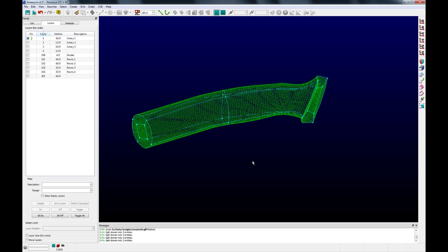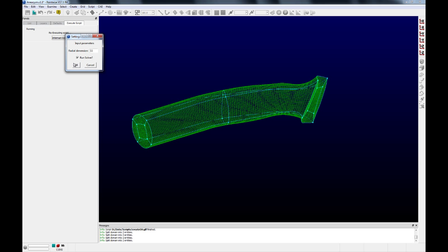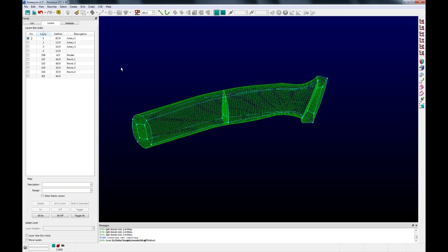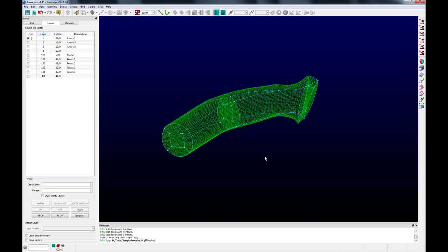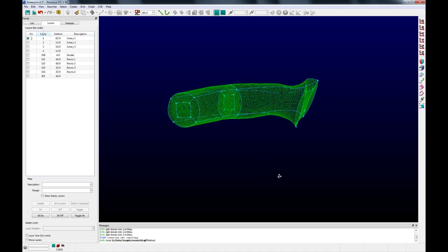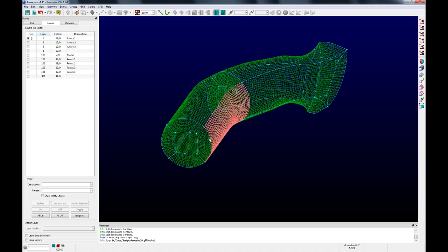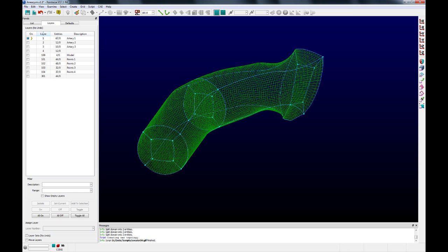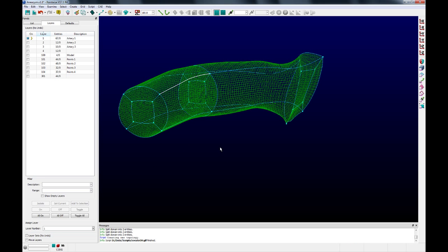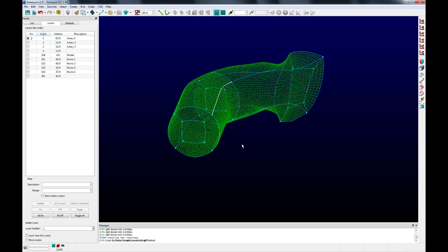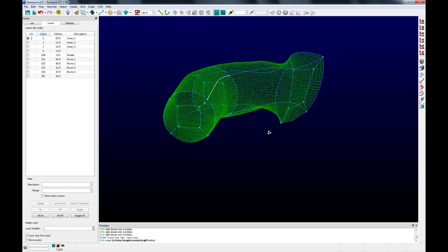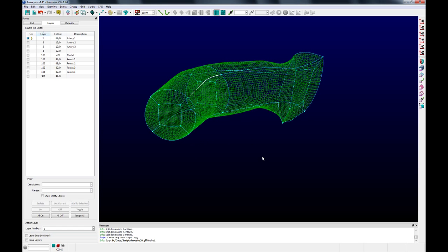We're then going to run the OH script one more time. We're going to accept the default settings, select these 4 connectors, and click Done. So we now have our OH topology defined, but we're still lacking some internal structure because we need to connect these points up on the interior of the OH topology. To do that, we're going to be using the copy and paste command in Pointwise. So we could draw curves manually, but because of the twists and turns, it's going to be a lot easier to just copy and paste. That way the connector already has the natural curvature that we want.